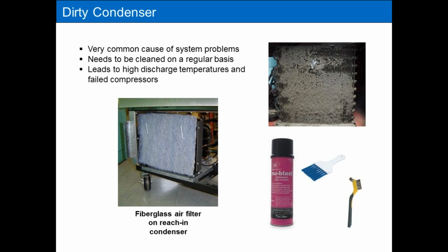Now I also have on the screen a sample picture of a filter, a fiberglass filter or even a mesh filter that guys put on condensers. Honestly, I'm kind of in between on whether this is a good approach or not. I don't have any empirical data on whether or not this adversely affects the airflow through the condenser. So let's assume that it doesn't affect the airflow. If you push that to the side, that is actually a very good technique to use to keep these condensers clean.